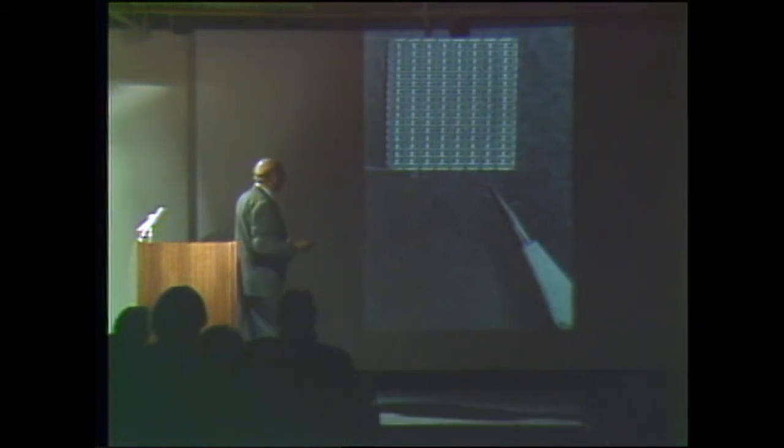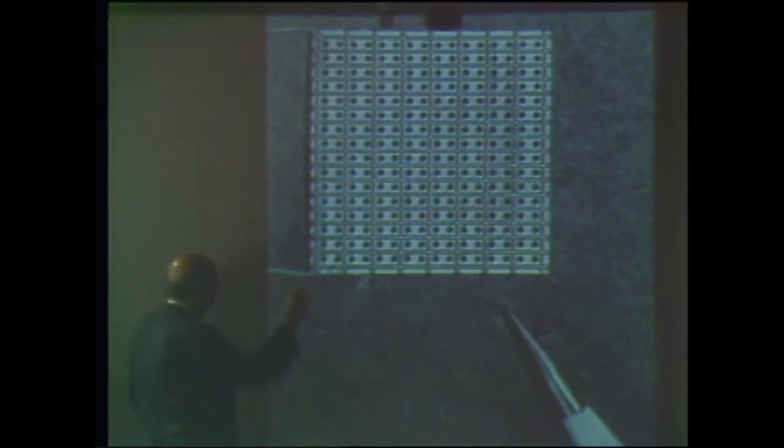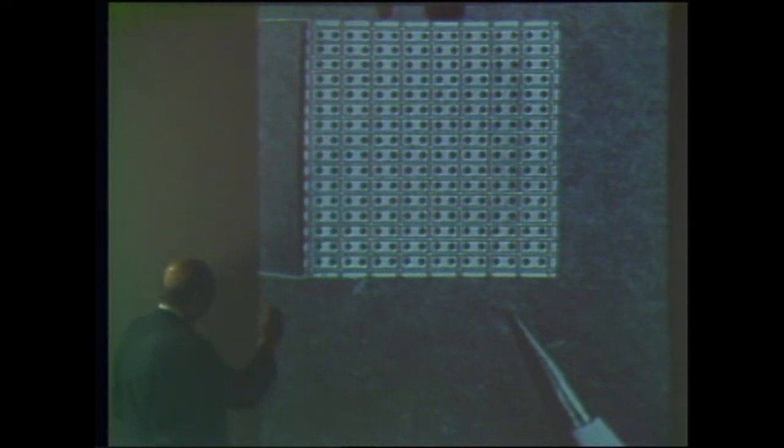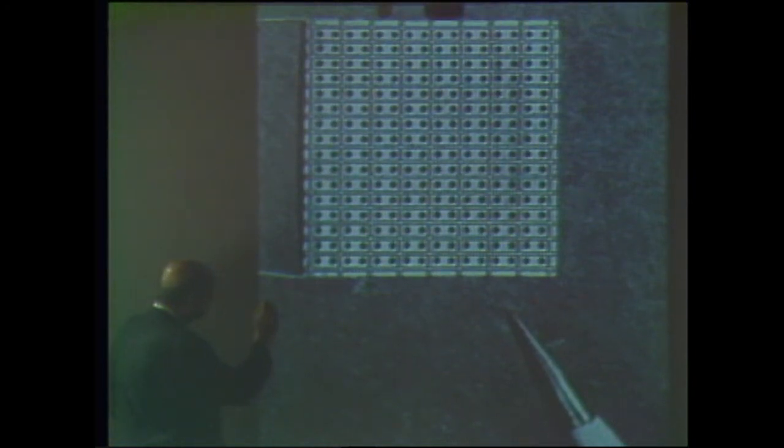And so one of the attempts that we made was to make a ferrite sheet that was stamped with holes, and then metal was sprayed on the whole business, and then the metal was cut along these lines, and you can see that that metal produced a winding linking them all, because the current went through the walls of the tube from one element to the other, and then from this hole to this hole, and another square like this on the other side, so that this made a winding that linked all the holes in series.